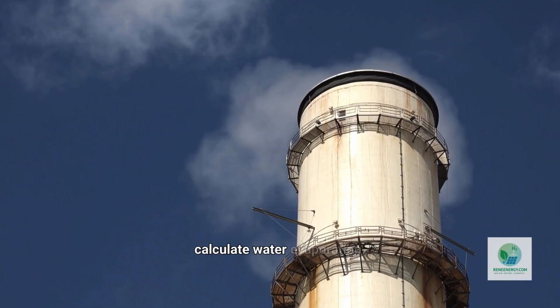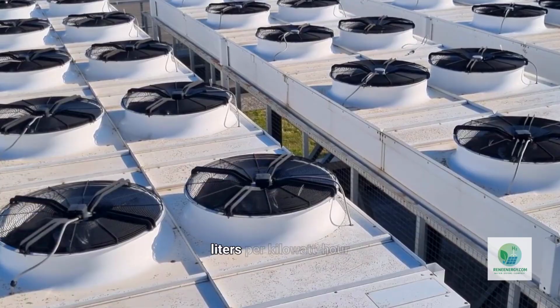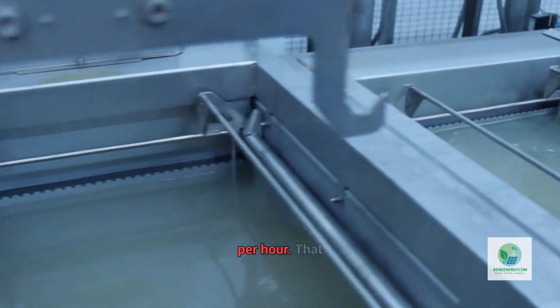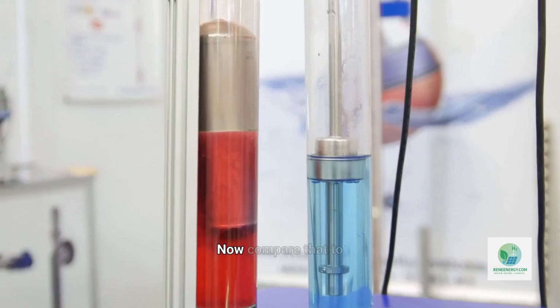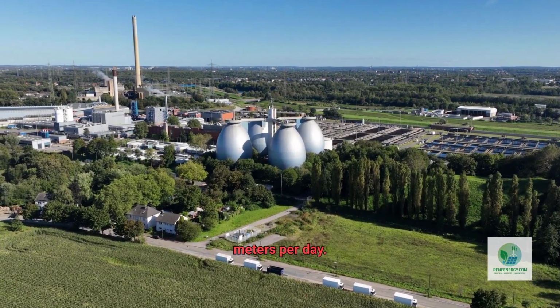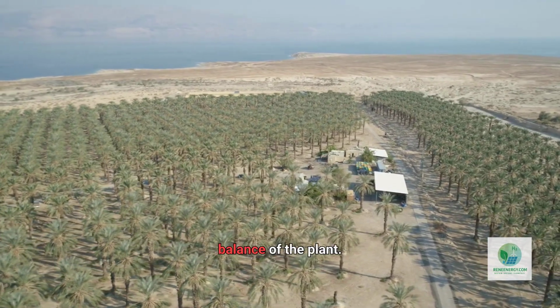But now calculate water evaporation. Using a typical evaporation rate of 1.5 liters per kilowatt hour of heat rejected, the plant loses approximately 26,550 liters per hour. That equals 637 cubic meters per day. Now compare that to electrolysis water consumption for hydrogen production, approximately 327 cubic meters per day. Cooling consumes nearly twice as much water as the hydrogen reaction itself. In an arid region, that changes the entire water balance of the plant.